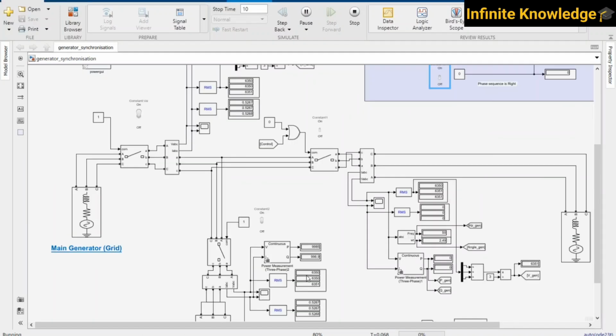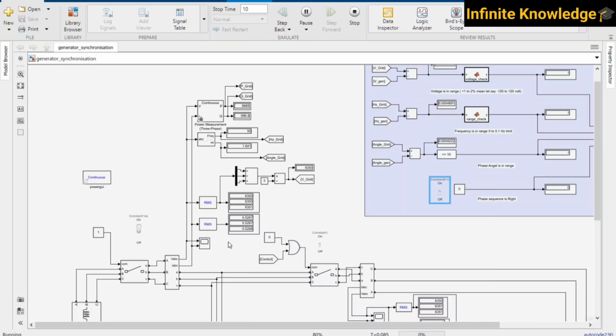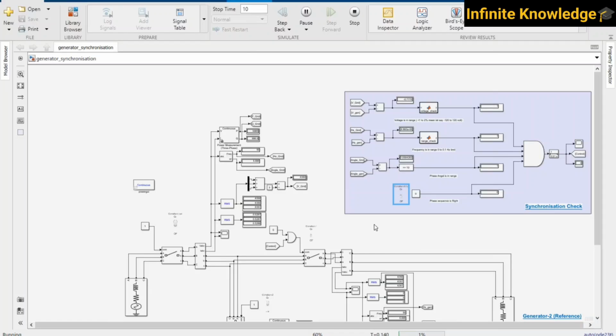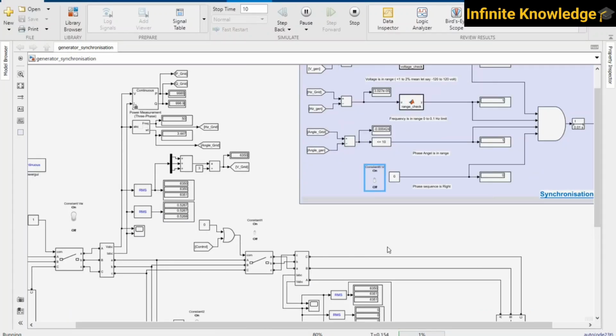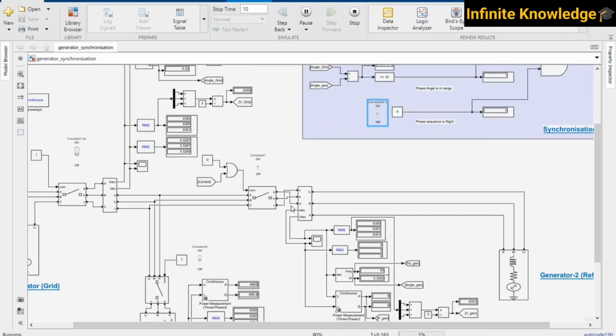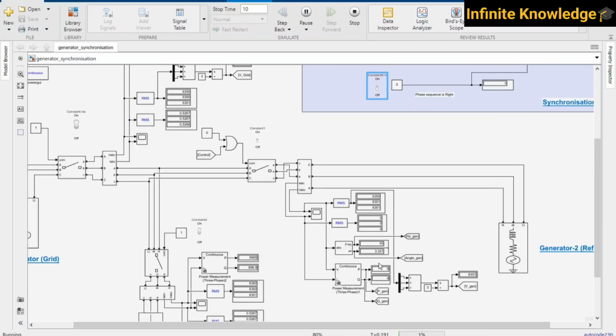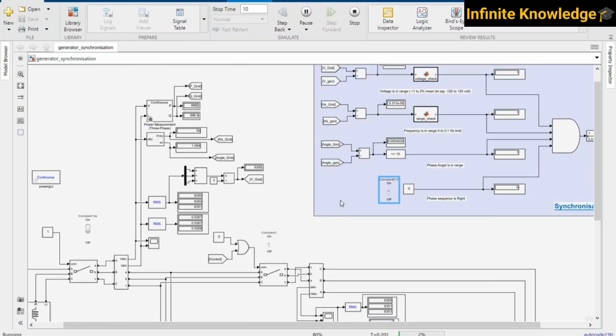So you can see 0.52 ampere. 0.52 ampere is being fed by this generator, and this is the power, 9985. Now I just turn on, and this generator, this breaker is off. That's why current is zero, and power is also zero. Reactive power is also zero. I just turn on this switch, which means the phase sequence is okay, and then finally we can start our breaker.